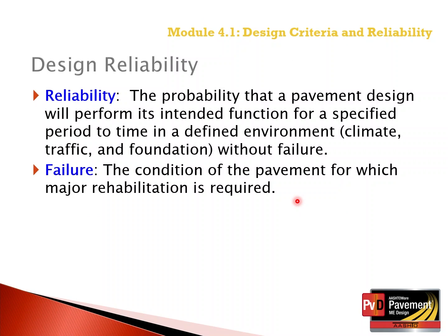So as a reminder, design reliability. We covered this in Module 3, but reliability is defined as the probability that a pavement design will perform its intended function for a specific period of time in a defined environment. And that environment includes climate, traffic, foundation, and other site factors, without failure. Failure is the condition of the pavement for which major rehabilitation is required.